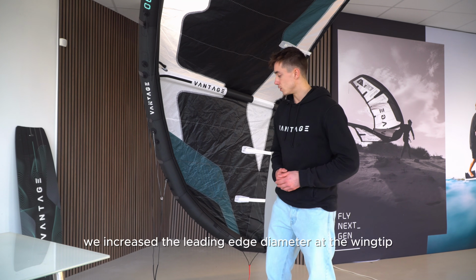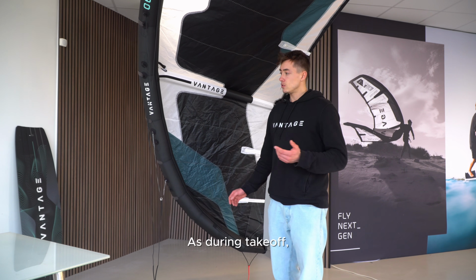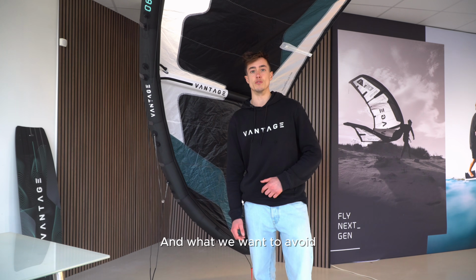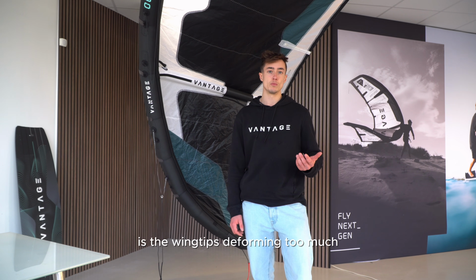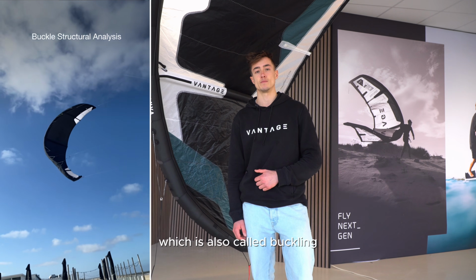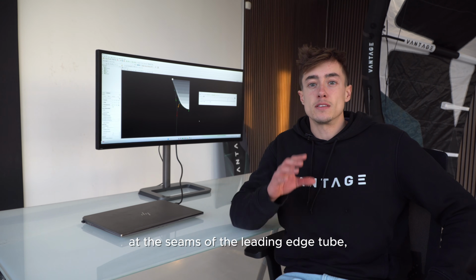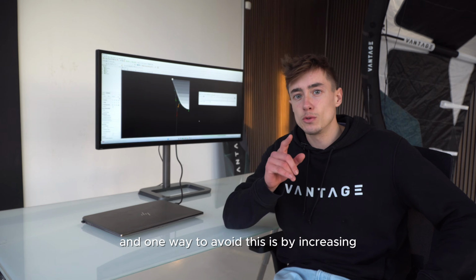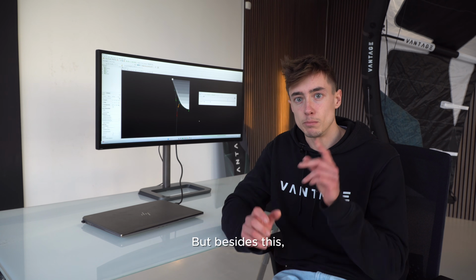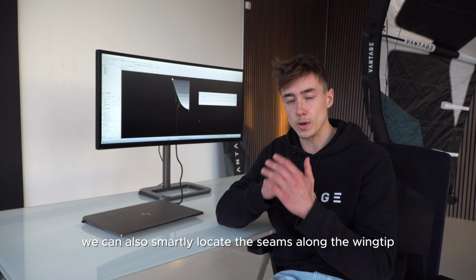On the other hand, we increased the leading edge diameter of the wingtip, as during takeoff, the wingtips experience the highest load. And what we want to avoid is the wingtips to deform too much or collapse, what's also called buckling. So buckling always takes place at the seams of the leading edge tube. And one thing to avoid this is by increasing the leading edge diameter. But besides this, we can also smartly locate the seams along the wingtip.